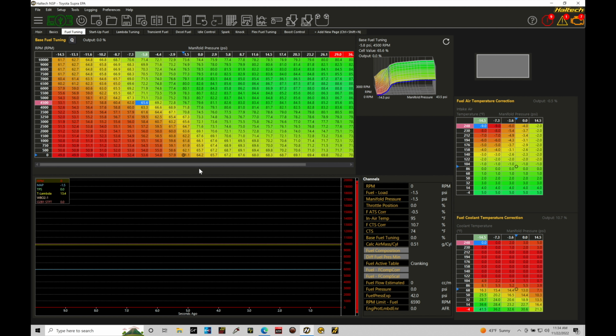And if you want to change your base fuel pressure, you do not have to retune the car. If you have a fuel pressure drop, let's say at higher load, high RPMs, maybe your fuel pump's not keeping up, it'll automatically calculate and recorrect your injector pulse width relative to that pressure drop. So it's something that I always try to integrate in all the projects that I'm personally working on with an Elite system, and I'm going to show you how to integrate that.